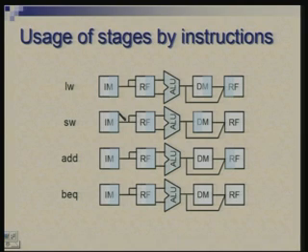Okay. So, for let us say devices like the register file, if I am shading the right half, it actually means I am reading, because I am shading the active part closer to the output ports, and shading the left half means that I am indicating a write action. So, similarly for memories, and the ALU of course gets fully utilized. So, either it is fully shaded or not shaded. In this you will see it is always shaded here. IM always gets shaded in the right half. DM may get shaded in the left half or right half.